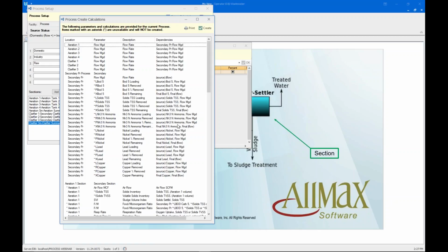So we're going to create that. We'll take our total plant influent flow and we'll divide, like on aeration, for example, we'll divide it by 4 and put that much into each one. Again, this is where your percentage comes into play. If for some reason we take one of the aeration basins out of service, well, it would now be each one of the tanks would be getting 33 1/3% of the flow instead of 25%. Next, what you see in the list is you see our secondary process. Remember, this was our file cabinet. We didn't define any parameters at this location.